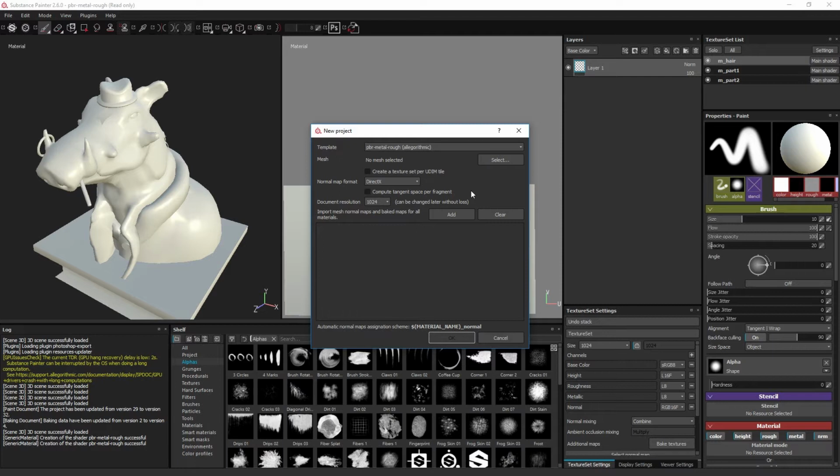So what you need to check for in the online documentation of your rendering environment is if it defines the bitangent, which is the z component of the vertex normal, in the vertex shader or in the fragmentation shader. If all three components are defined in the vertex shader, set the button to off, and if the bitangent is calculated outside the vertex shader, set it to on. And again, if you are using Unity, set the button to off, and if you're using Unreal, set it to on.